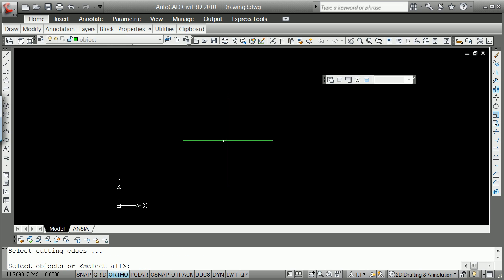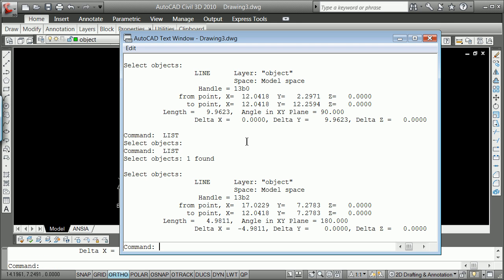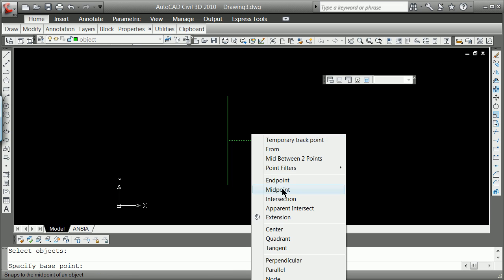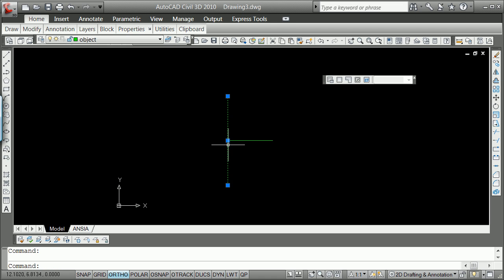Now I'm going to point out as I'm doing, the structure doesn't have direction, because right now I don't know which line is going where. So in all reality, very often on this pole it goes all the way through. I might want to check that this structure, as I list it, is drafted in the right direction. It is going 90, so that's going in the right direction. If I think about going away and this is going 180, I might want to rotate that about its midpoint 180 degrees. Now at least I know something about the contiguity.